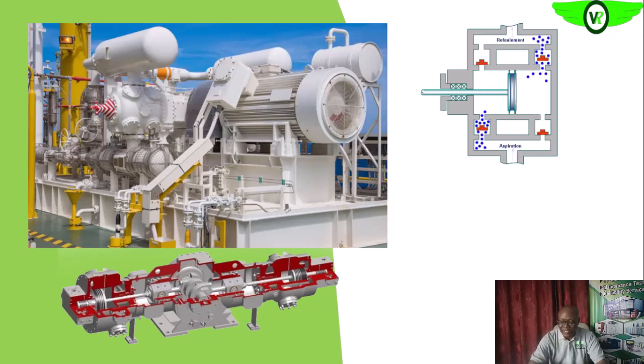You see that it is compressing at both ends. So it's like having two single acting reciprocating compressors. When one end is compressing, the other end is admitting gas into its chamber, and as that end compresses, this one is admitting.